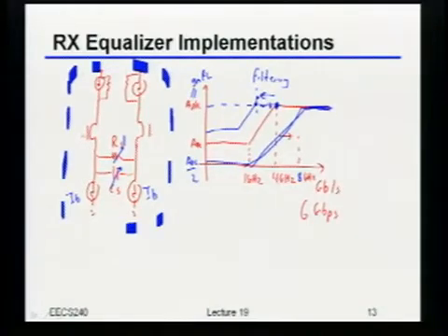So any other way you guys can think of to try and create another zero? The ladder network. Oh, okay, so yeah, I could try and come up with some more sophisticated network down here. That's actually true. That turns out to usually be pretty difficult. There's one more thing you can actually change here and not spend any extra power. A feed-through zero? Okay, yeah, you're right. You could create some sort of feed-through zero. Getting the sign right is a little bit tricky. You have to cross-couple things. That's actually not a horrible idea. There's one more thing that I claim is actually maybe a little bit easier to design.